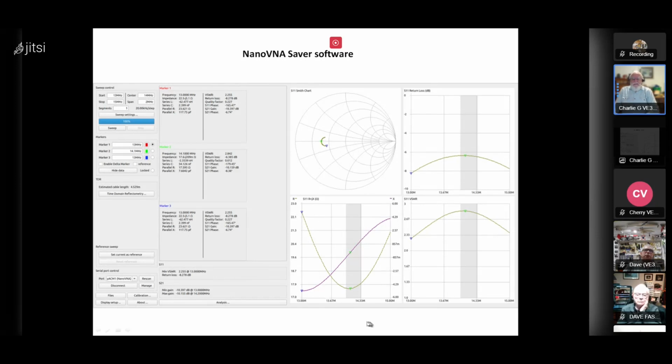But when I look at things like the standing wave ratio and the return loss, they kind of suck. And they kind of suck because although my antenna is resonant at the right frequency, I'm not anywhere near the 50 ohms here. I'm way out to lunch. If I look at these graphs here, for instance, of the impedance, in terms of reactance, the purple line is reactance here.